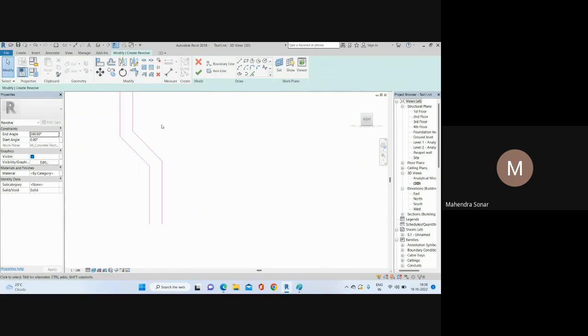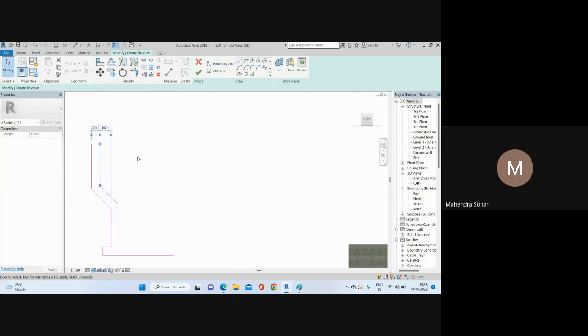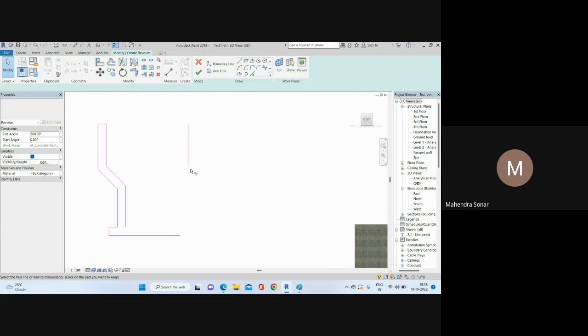And after that you need to add the slab here. So suppose my toe is 300, and slab thickness is also 300. Then after that you need to decide your diameter, so this diameter and this diameter. So just consider our tank, this diameter is 3 meter, so I will just copy this 3 meter. So this is your external face, right. Then after that you can just trim here, so you can get the exact center here. So 3 meter is your diameter.